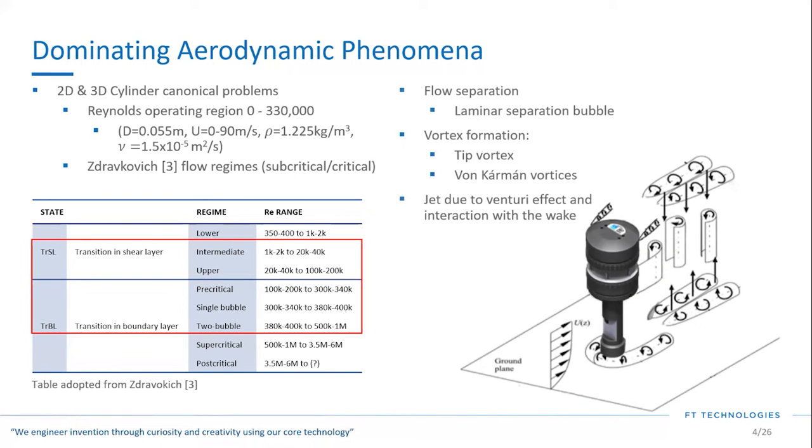As for the physics that we expect to see, there's flow separation externally as well as internal. There's vortex formations such as tip vortices and von Karman vortices, and then a jet due to the Venturi effect inside of the cavity, which will then interact with the wake.